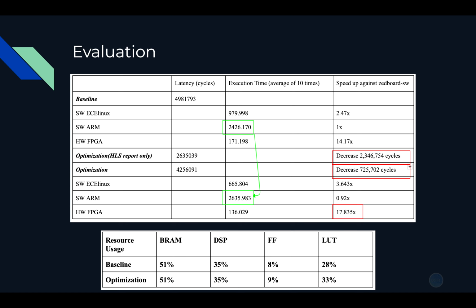Regarding hardware usage, because of the routing feasibility issues, we have utilized most of our hardware resources to optimize our project. For instance, our lookup table has already reached 33% utilization in our efforts to optimize latency. So, overall, these accomplishments are particularly remarkable given the challenges we faced, such as processing over 32,000 input data points and executing 14 stages of FFTs.